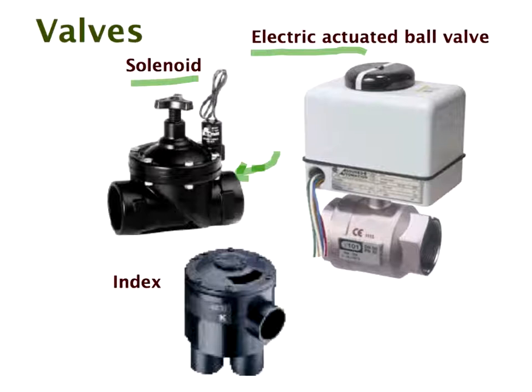So if you're using a solenoid valve, and you don't have a bleed to allow that last couple of feet of water to drain, you can put a bleed around it, or you can use an electric valve. An electric valve will stay open until the signal comes for it to close. So sometimes in freezing conditions, on the flush return, people will use an electric valve.